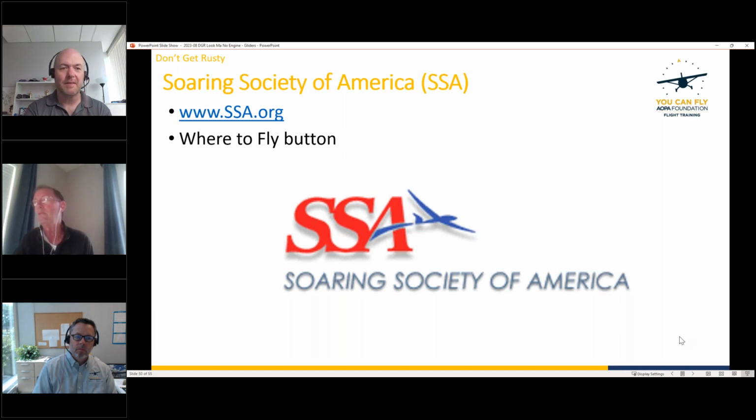And I would have 80% of the battery capacity still available if I wanted to do what's called a retrieve, which means you've flown out beyond normal gliding distance of the airport and it's clear you're not going to get back. You can restart the motor and use that to get back. So the motors are really not designed for continuous cruising flying. There's not enough battery capacity to do that. They're designed for taking off, getting up to altitude, and then shutting them down and making the rest of the flight as a glider.